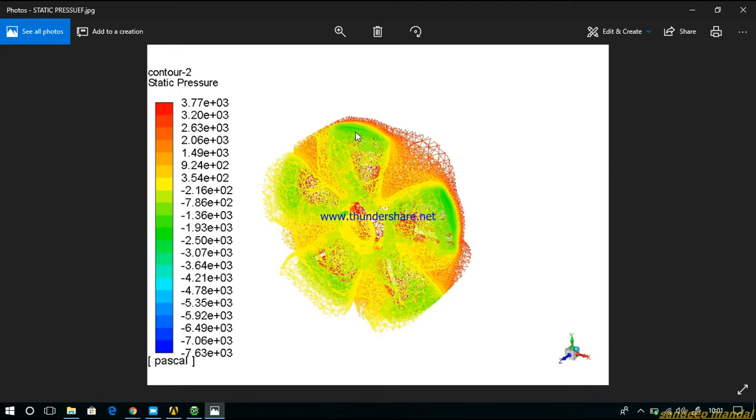because of the blockage of this blade. When the air enters from the inlet domain, the blockage is provided by this trailing edge, and more blockage is provided by the trailing edge because it is radially outward with the pitch angle of 40 degrees.